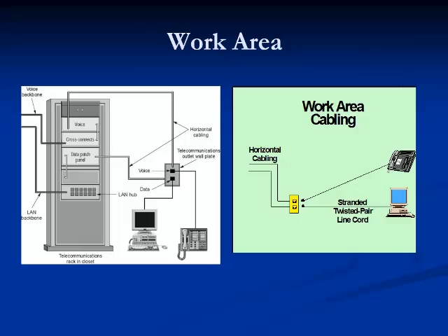Modular patch panels or patch cords are used to provide the connection between field-terminated horizontal cables and network connectivity devices such as switches and hubs. Because of their role in structured cabling infrastructure, modular patch cords are always the weakest link. Whereas horizontal cables contain solid conductors, patch cords are made with stranded conductors because they are more flexible. The flexibility allows them to withstand the abuse of frequent flexing and reconnecting.